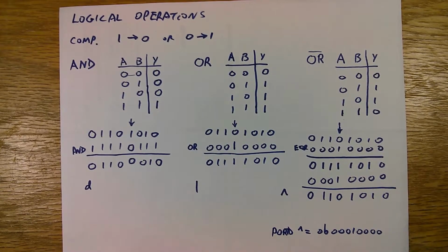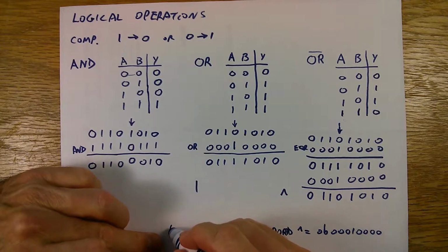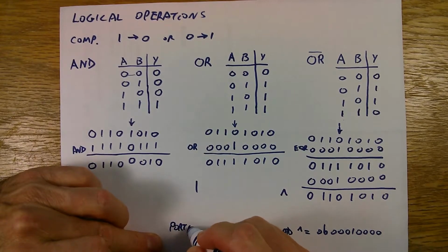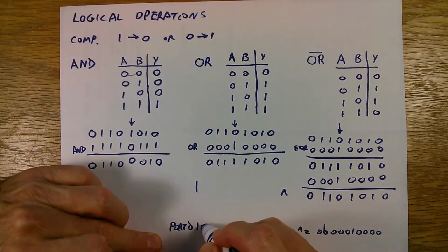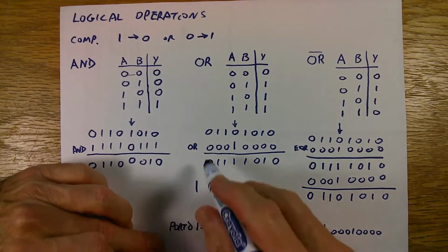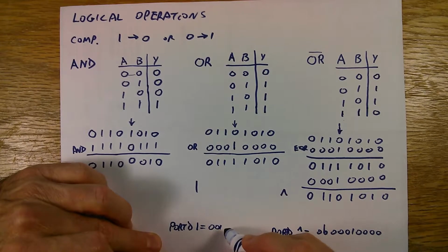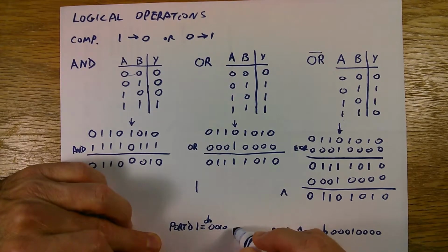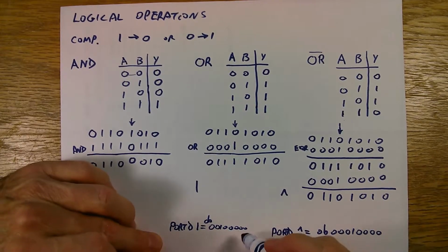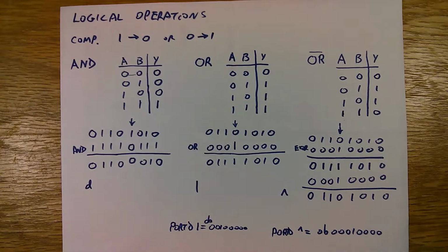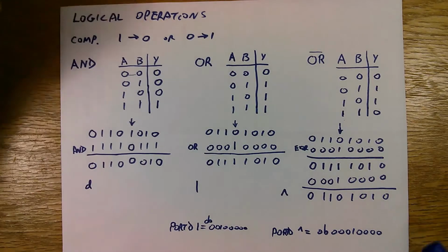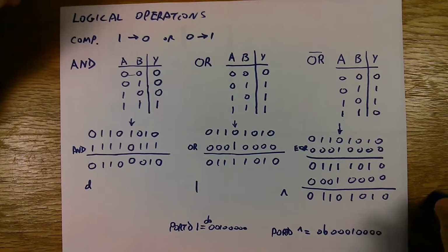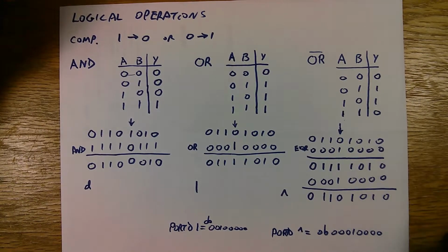You could do that with this one here. We could go PORTD OR equals, and then the same number, oops, put the 0b in front. 0, 1, 2, 3, 4. So that's how you do it in your software. And then same thing with the ampersand, which I can't write obviously. So that's some basic logic operators on binary numbers.